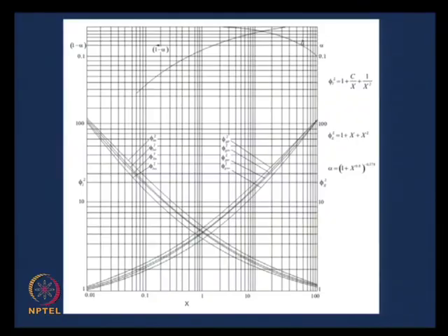Okay. So, here you find that if we plot alpha versus x square or 1 minus alpha versus x square in this particular graph that I have drawn, interestingly, for all the 4 cases, in this presentation which I have prepared, we find that while in phi L square versus x, you have 4 separate curves for laminar, turbulent, and so on, here we have one particular graph.